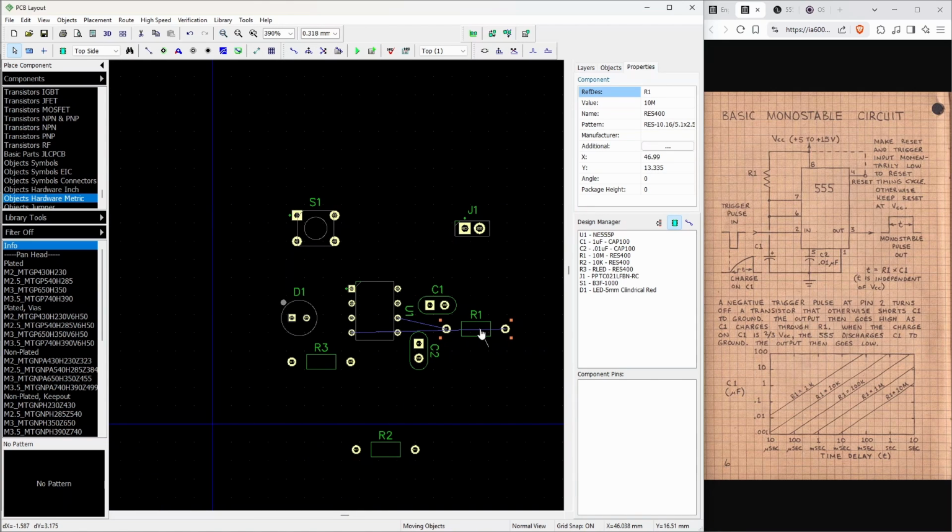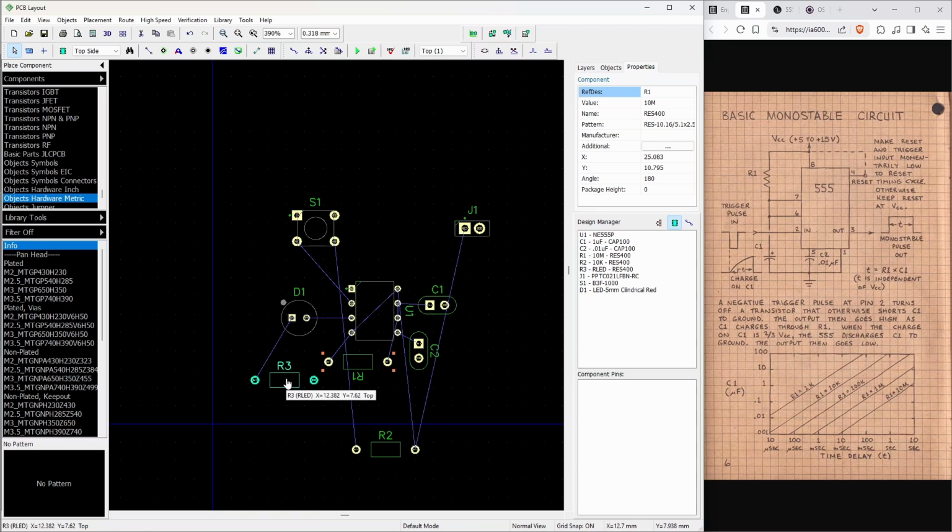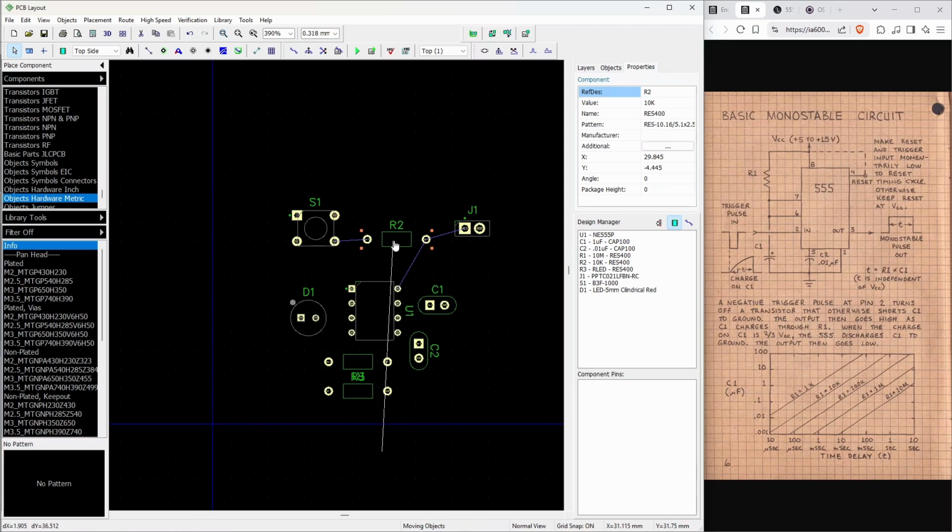This resistor is going to be connected between these two pins. So it looks crazy the way I'm doing it, but this can actually happen right between those two. So we can do that very easily. And we can actually put this one down here if we wanted to. It depends on the shape of our board and how we want it to look. But here's the pull-up resistor for the switch, and I will move this maybe like that.